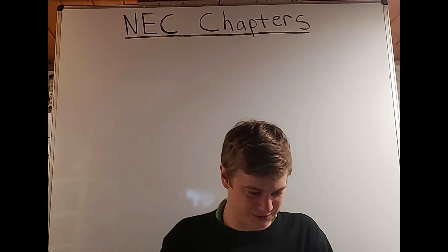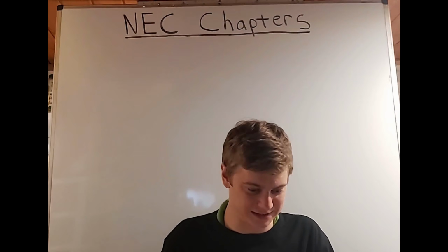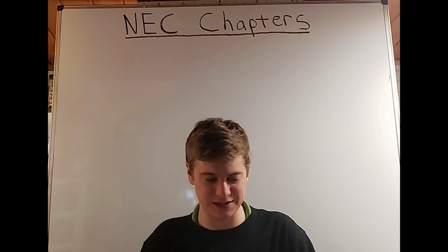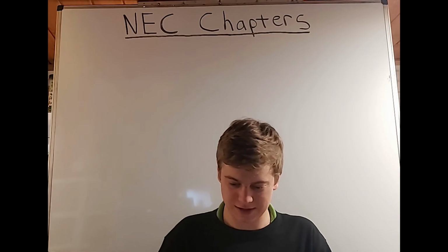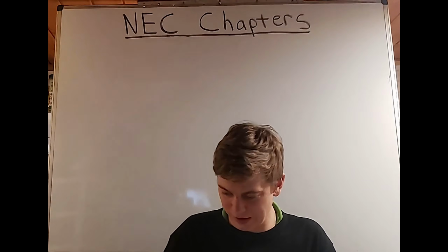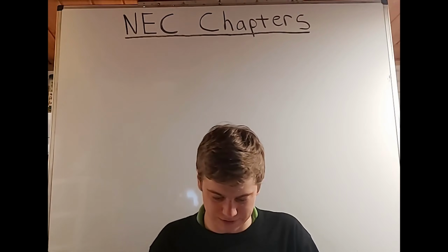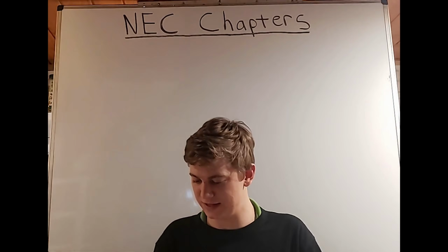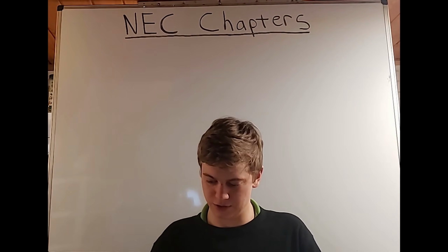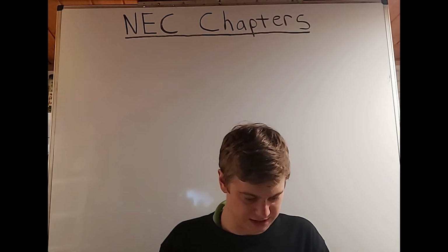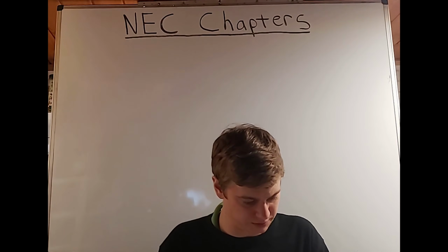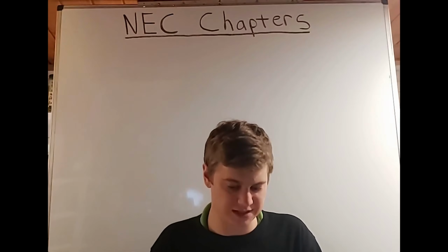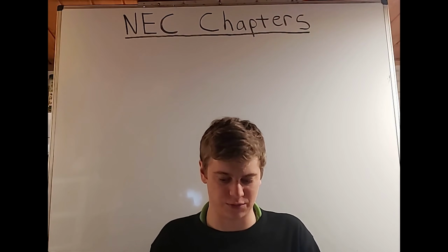Moving on to table 310.17, which is ampacities of single insulated conductors in free air. This is much less commonly used than table 310.16, as well as the other tables after this as well. We're going to go into Article 311, which is medium voltage conductors and cables. It's very good to know that if they mention medium voltage, then you're in Article 311. We see the thickness of insulation with table 311.10(B) and (C). We see the minimum size of conductors with table 311.12(A).